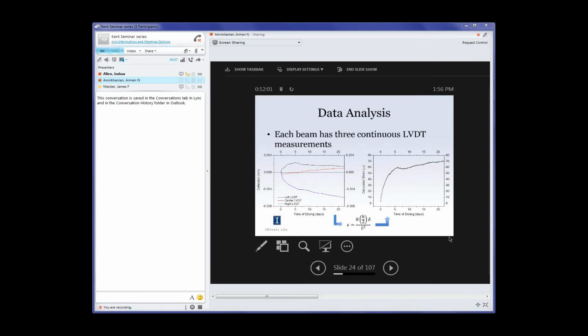We'll talk about that. Yeah, but it would still ultimately be conservative then, wouldn't it? Because I had the same concern, especially based on this plot, because you said the beams were not fixed, right? So you see slight movement of the center LVDT showing that it wasn't fixed. But if you look at the one on the top of the plot, it's actually starting to revert back, which to me really just means pushing off of that LVDT and pivoting to favor the other. Yes, the other LVDT, because that's where you see that one continuing to accelerate.